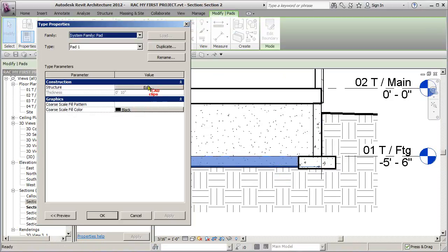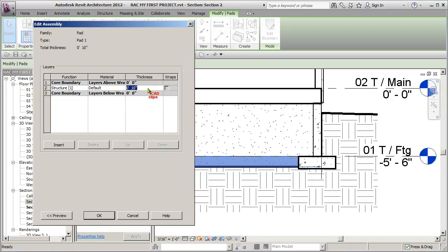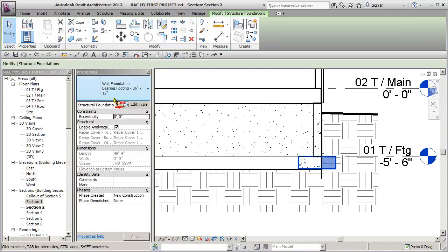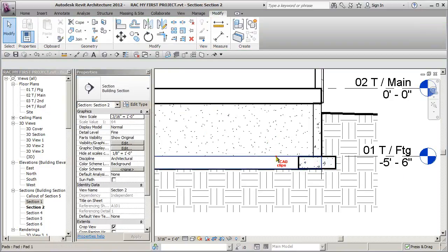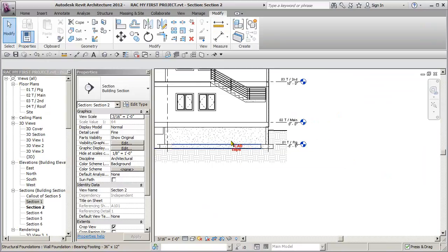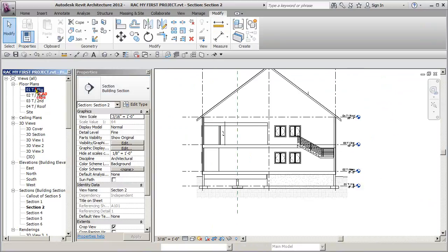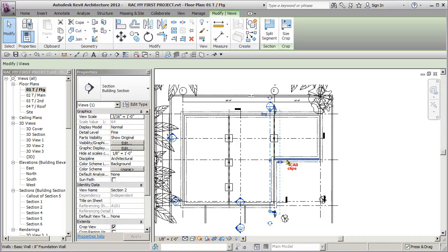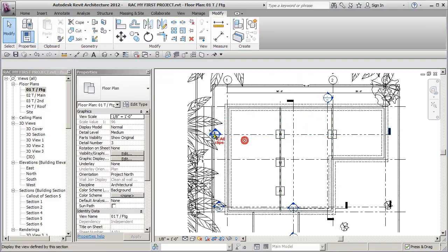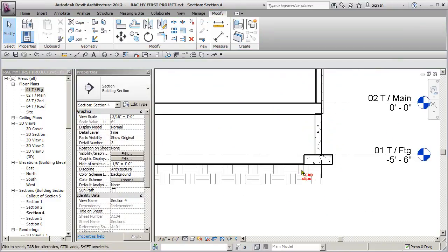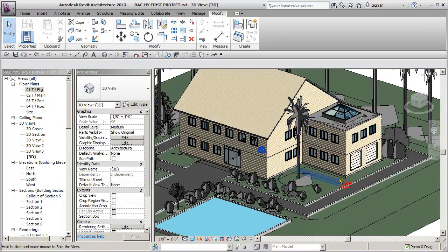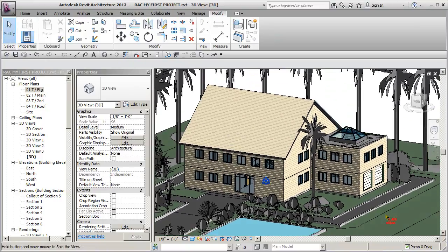Now my pad, did I change that thickness? Is it supposed to be 1 foot or something? Must be. This is a 36 by 12. Yeah, so this has to be a foot thick, and then I turn it off, hide the element. Then you never see it. That line again is the footing beyond. If I go back to my top of footing, what I'm seeing there is the line beyond. Similarly here. If I pull this back, then I won't see that line beyond. So that's our footing pad in place. It's going to remove and excavate that material from the underside of our building.